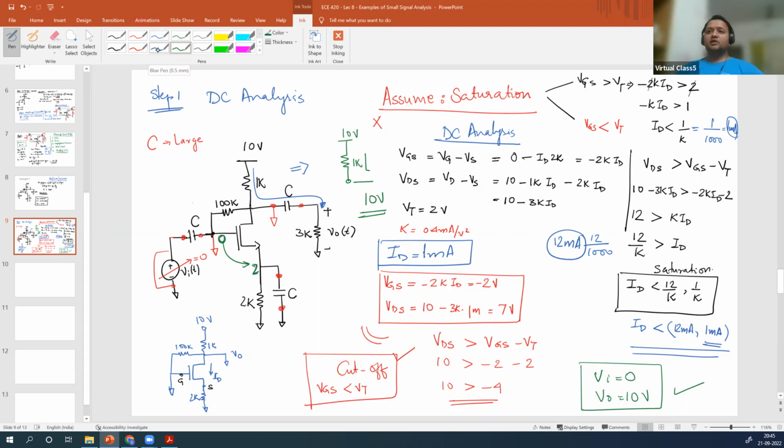Right? Gate bias you will introduce. At this point, you will introduce a fixed DC bias value. You will introduce a resistor R connected to ground. In that case, what will happen? There will be a DC current path. Follow the pink line. There will be a DC current path to flow to ground. When there is a DC current path, you will have a DC voltage applied here.